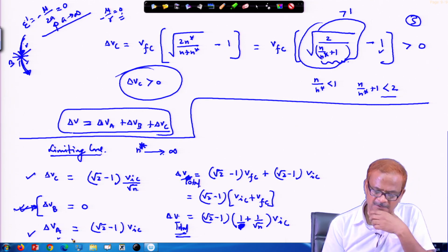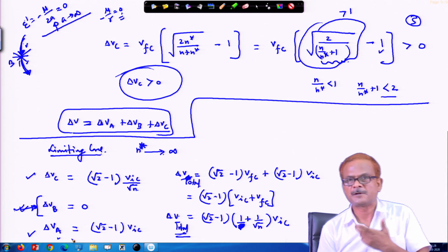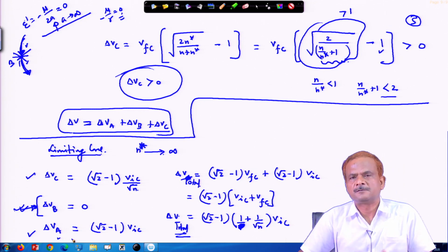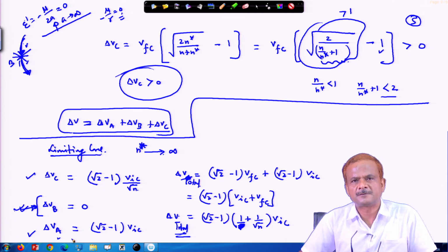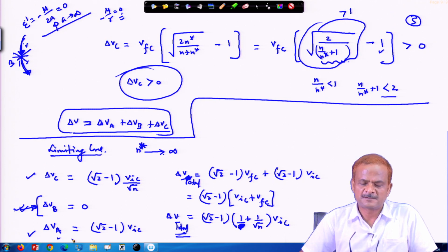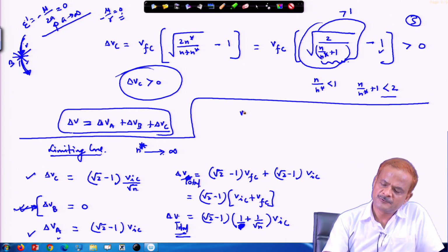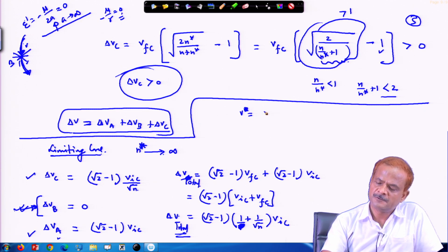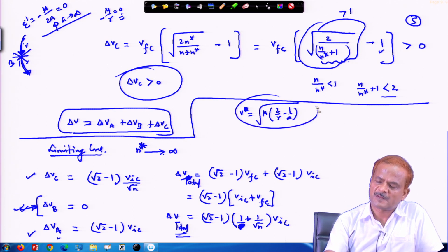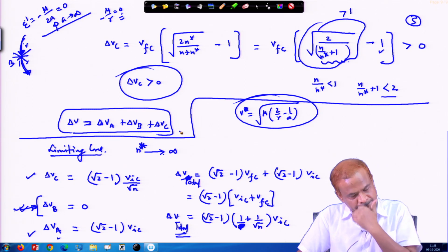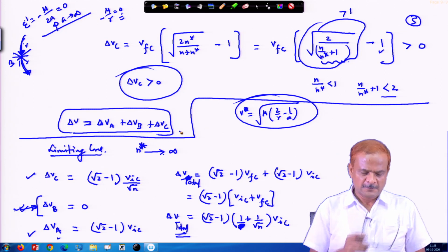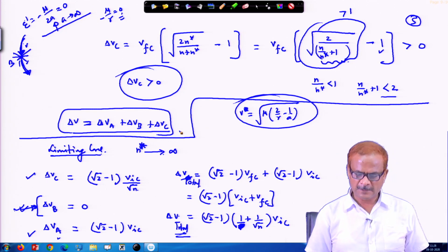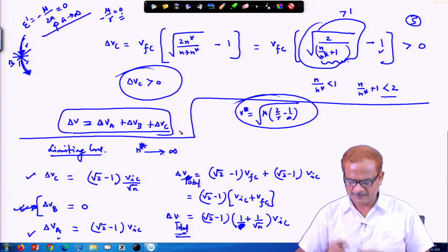So, using this technique, if you have to send the object in the parabolic orbit, you can work it out. The satellite you have to send in the parabolic orbit, or multiple orbits, different kinds of orbits can also be mixed up. And what is the simplicity? That you have to use this equation, V squared equal to mu times 2 by r minus 1 by A, which we have earlier derived as this Vis-viva integral. So, by this we have finished the bielliptic transfer.